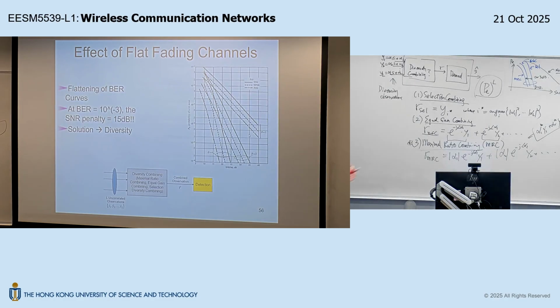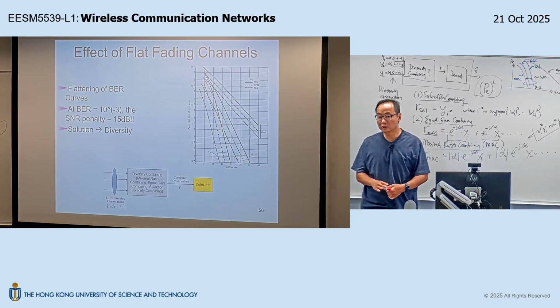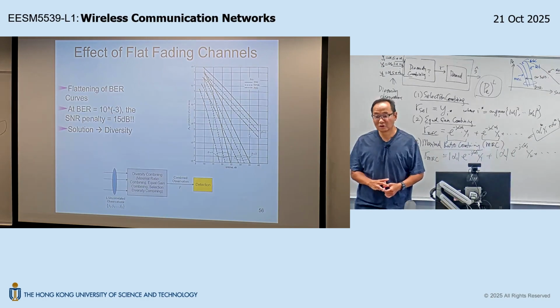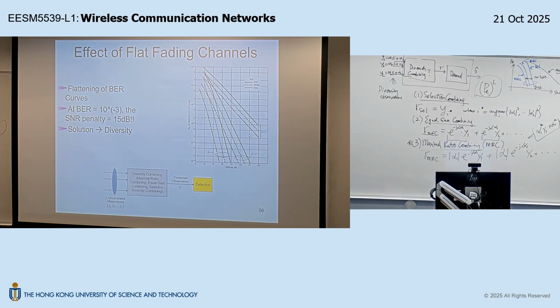If, after the link budget analysis, I really need to have 4th order diversity to meet that coverage target, then what can I do? In that case, I have 4 receive antennas, but then I may need to have 2 RF and ADC chains, so that I still partition the preamble into 2 halves. In the first half, with these 2 chains, I will be able to estimate, say, alpha 1 hat, alpha 2 hat. In the second half, I will be able to estimate alpha 3 hat, alpha 4 hat. Is that okay? So things like that, okay?